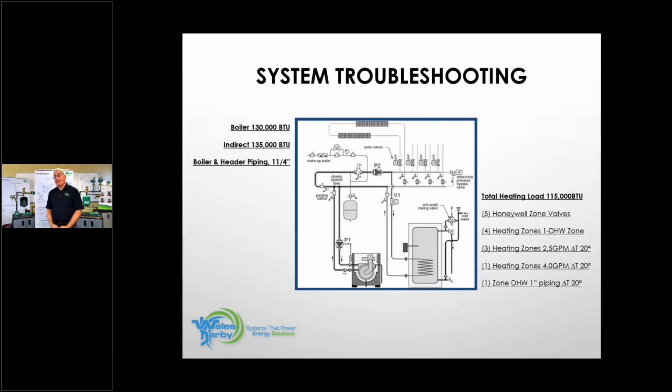Because Miss Little Sally's mom is not happy now, so that's a big one. Make it a circulator. Absolutely right. Make it a circulator to domestic. Absolutely right. And here's what we would tell you to do: add a circulator and take it off right here. John calls that direct hot water. Pull it off right here. Prioritize it. This way we only drive one circulator. We don't need to drive this circulator, and we can fix that domestic hot water problem.